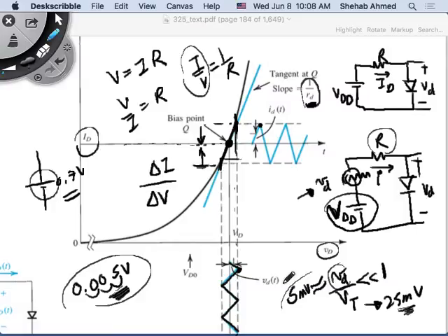So the benefit here is, for example, useful when you're designing a voltage regulator. It's really not useful for amplifying signals. But when you're designing a voltage regulator, you have a power supply. We talked about flicker of the lights before, right? All power supplies have a line regulation limit, meaning they operate between a certain value. There's no such thing as a 10 volt power supply. You will measure it as 10 volts plus minus something, right? This plus minus something is ripple, right?